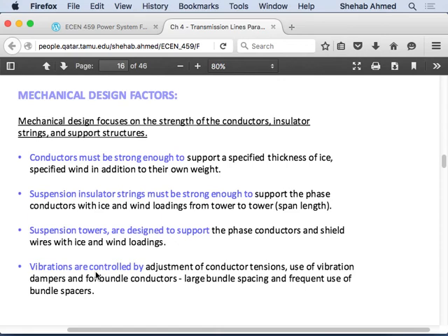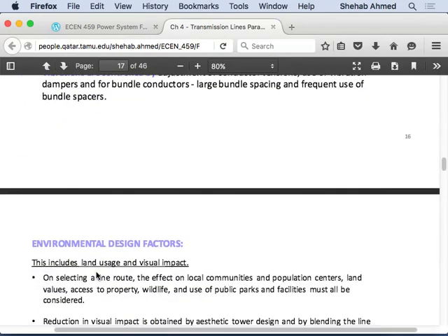Like an electrical circuit, if you provide it with current at its resonance frequency, then the impedance will basically be decreased considerably, right? If you provide a voltage at its resonance frequency, then the capacitance and inductance effects will completely be eliminated, and you just have the resistance effect, which is small in a power system, which means you will have large currents, right? So mechanically, it's the same. There's a resonance frequency for the line. For any mechanical device, if you vibrate the line at its resonance frequency, the vibrations will not be damped. They will be underdamped, and this line can be vibrating even more, right? So we add these vibration dampers along the line.